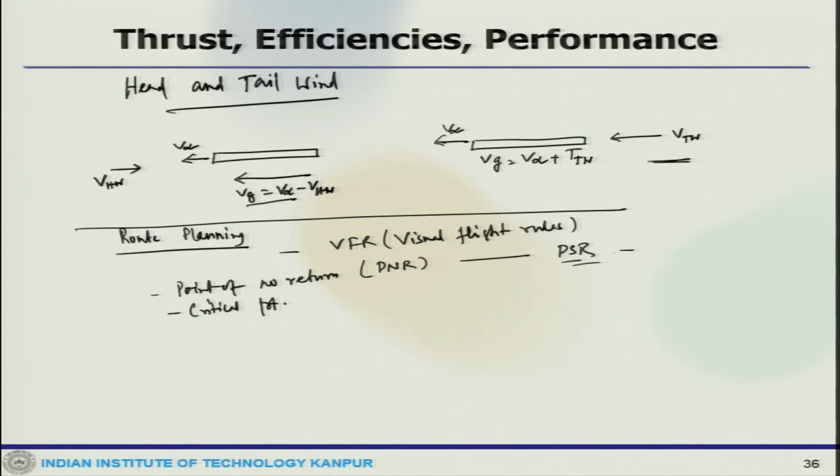There are a number of methods which can be used to calculate PNR or PSR, and one of the most favored uses what is called specific fuel flows, SFF. So, this is mostly used. These are calculated by dividing the planned cruise fuel flow by expected ground speeds towards the destination and towards the alternate field.